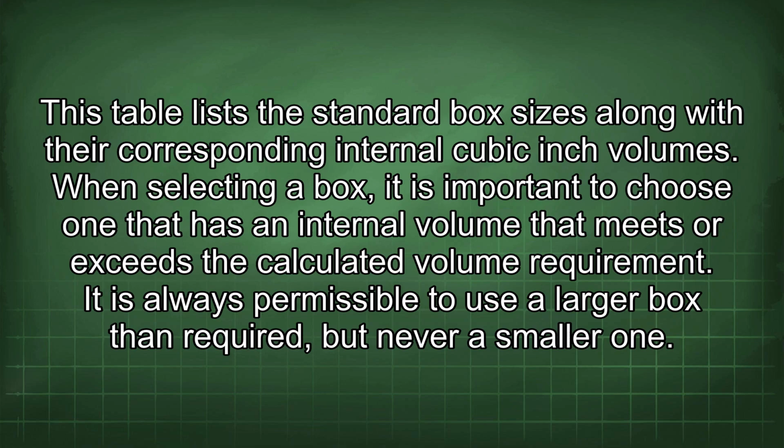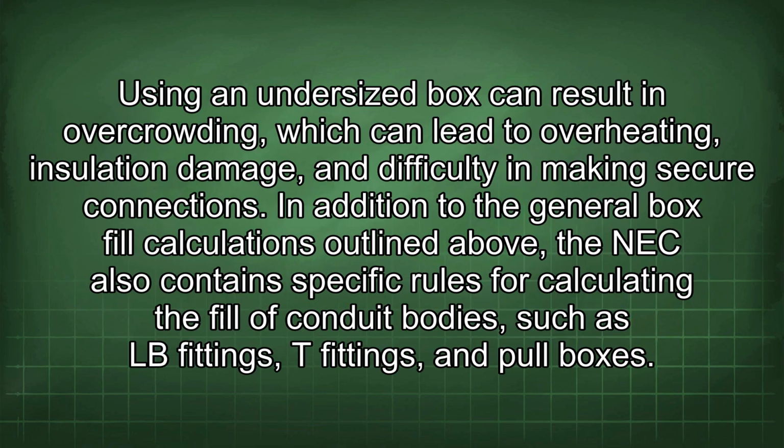When selecting a box, it is important to choose one that has an internal volume that meets or exceeds the calculated volume requirement. It is always permissible to use a larger box than required, but never a smaller one. Using an undersized box can result in overcrowding, which can lead to overheating, insulation damage, and difficulty in making secure connections.